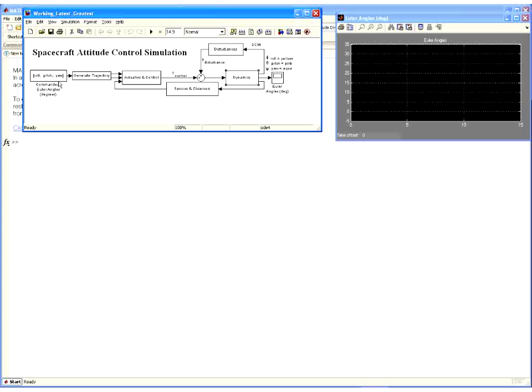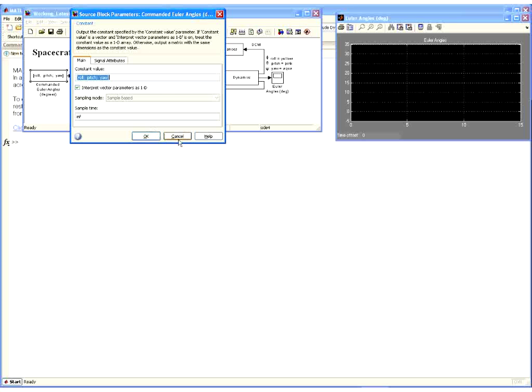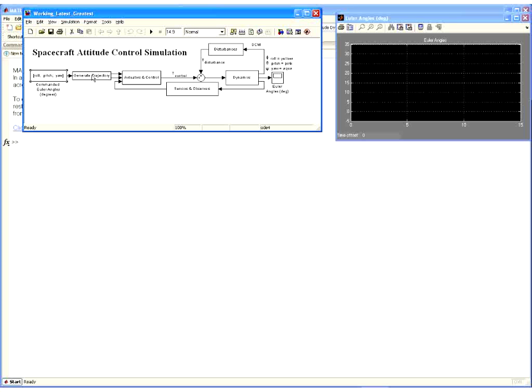I've previously introduced, we will command some turn, roll, pitch, or yaw. I'll teach you how to generate a good trajectory, a realizable trajectory to accomplish that command. That will be sent to a controller. If you wanted to achieve this command, there's a certain torque signal required, and the controller will calculate that torque signal. That required torque signal will be sent to an actuator, which produces that control torque. The control torque we can create, but the disturbance torque we can't.